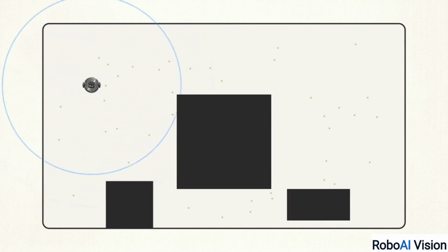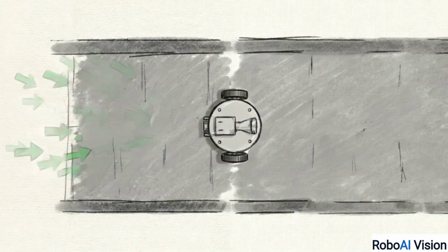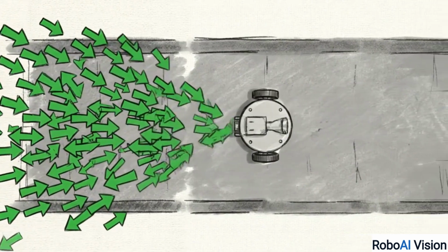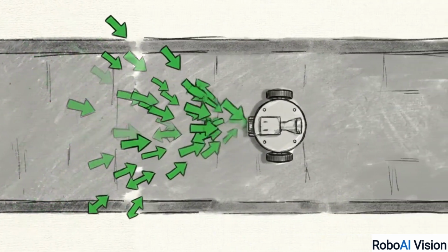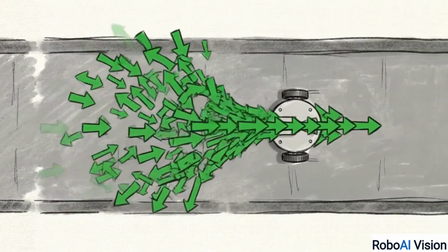As the robot moves, its LiDAR sensor measures the distance to the walls. AMCL compares these live measurements against the map, discarding hypothetical locations that don't match. By combining this with wheel odometry, the remaining particles cluster around the actual position. This becomes a rigorous process of mathematical elimination, repeatedly culling impossible locations until the most likely pose is identified.